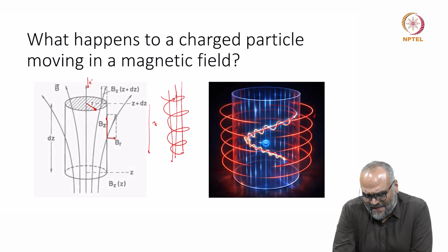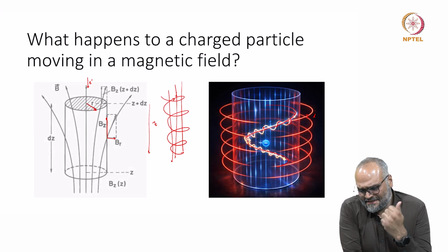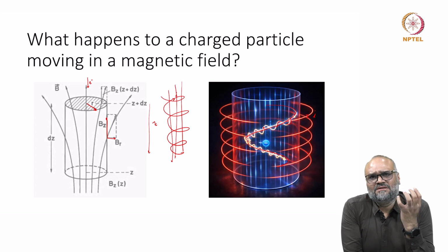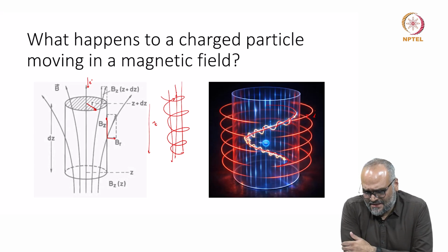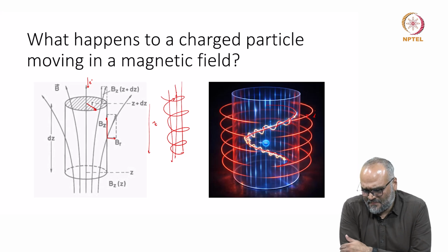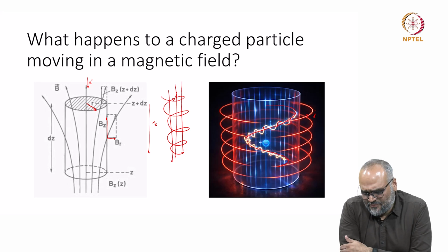But the point is, with the force that is actually acting, although this is not a very accurate description, when there is a current carrying conductor like a coil, which is analogous to an electromagnetic lens, the trajectory of the electron beam follows a helical path. Now, for the exact derivation of the strength of the lens and the trajectory that an electron beam follows, you can always use more accurate calculations and finite element method simulations to compute them.